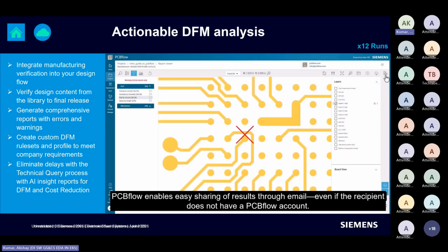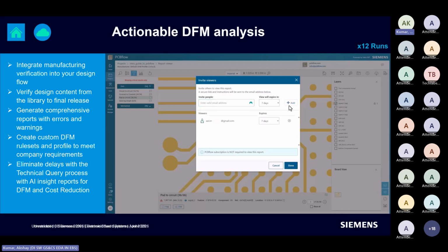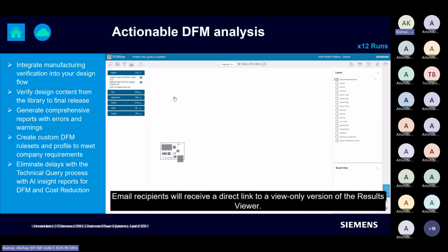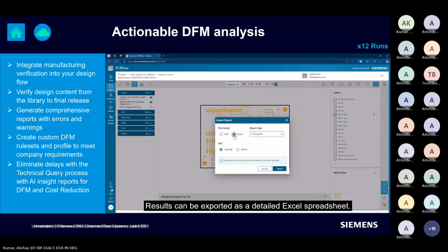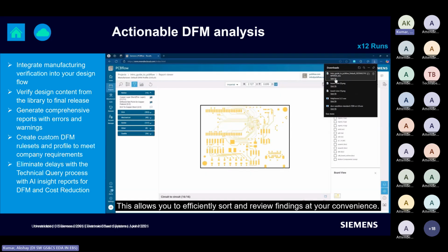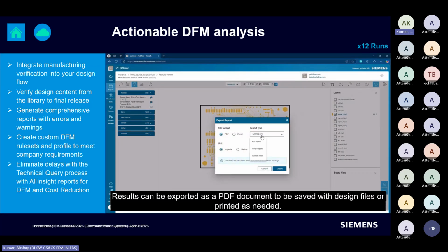All these DFA checks become much more crucial when you are designing. You will normally be doing this activity by receiving input from your supplier. Instead, we are asking you to do it when you are designing the board or when you have designed the board, at least do them. So you can access the detailed report in terms of an XLS file, as I was mentioning. And you have the option to extract only the flagged violations, or to extract the complete report. That's totally your choice.